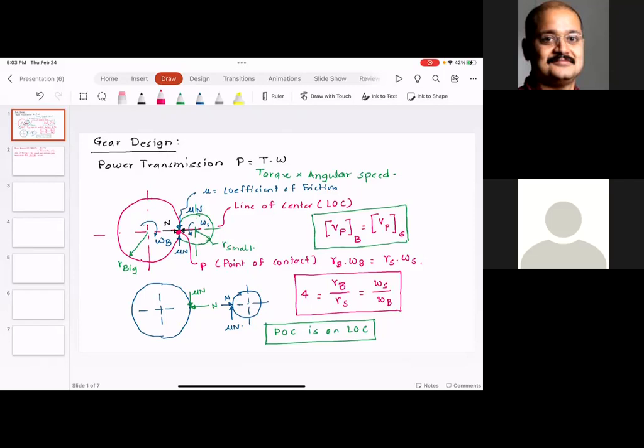So all that stuff. But then the problem with that is belts do not last forever. Chains, on the other hand, can last forever as long as they are maintained well. So then there is this design philosophy. Should I go with a timing belt, or should I go with a timing chain? Probably Hondas and Acuras adopt this timing belt philosophy, wherein they say that's okay.